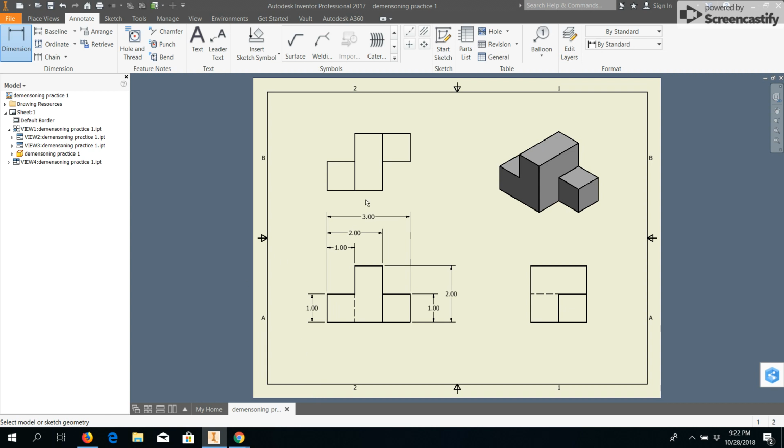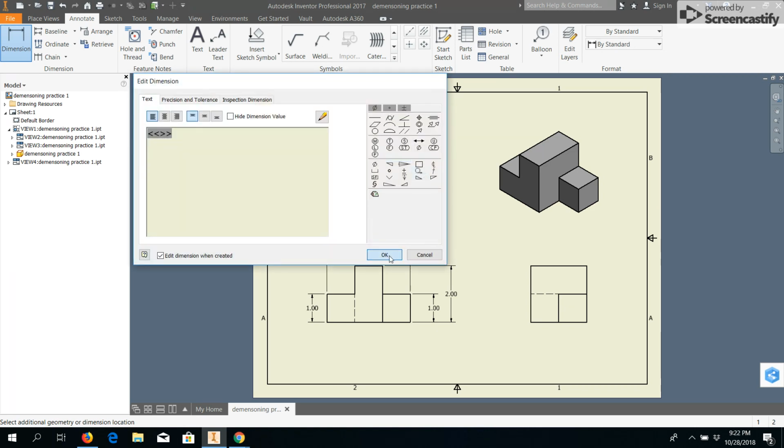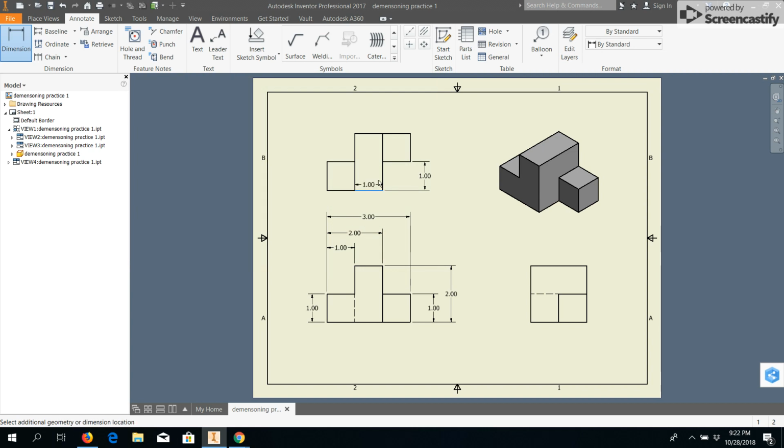And so next we have the depths, and I put it over here just so I wouldn't be crossing the whole picture. So finally we have depths. I could do that on this view, the right view, or the top view. The top view shows more contour, so I'm going to use that. I'll do datum dimensioning like I did before. I'll start at the front and go to the next line, pull that over so it's between views, and then start at the same place and go to the top. It gives me my overall.